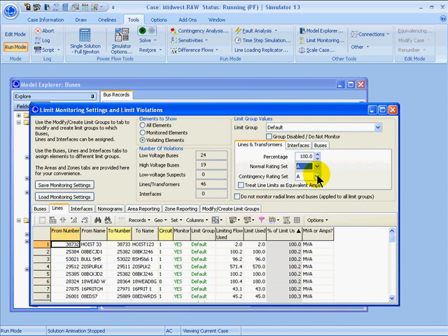Often, power systems will be modeled such that under contingencies, higher ratings are allowed to be used. So you might have a situation in which you specify a B rating set for contingencies and an A rating set for normal, and the B ratings might be at least equal to or greater than the A ratings. The contingency ratings are then used by Simulator during contingency analysis and also the other tools that might invoke contingency analysis, like the ATC tool or the security constrained OPF.